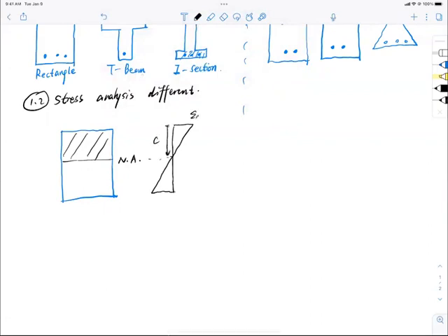And the concrete failed, of course, at 0.003 of the compressive strain, right? And I have a reinforcement, say somewhere here, and that is the epsilon s right here. So the depth of the section is right here, ds. And of course, when we do analysis or design for the concrete beam, we always ensure that Fs is equal to Fy, right? It's the yield strength of the bars.